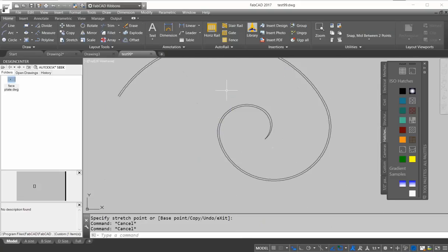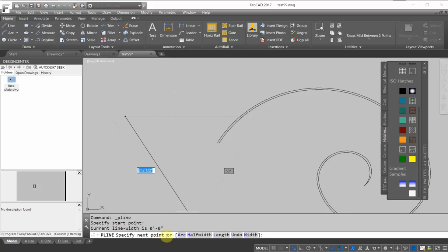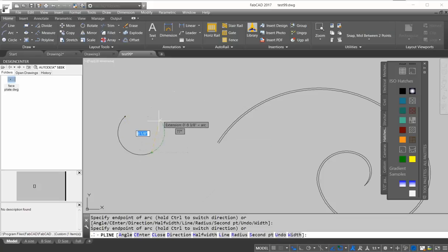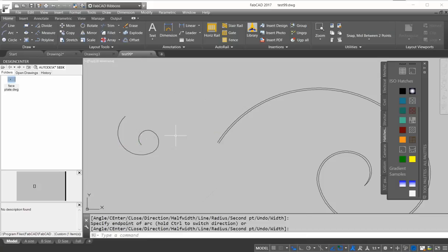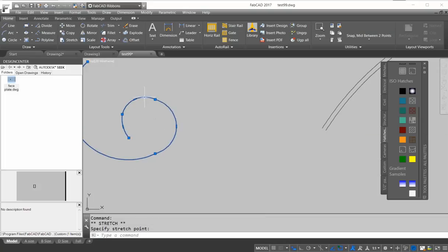All right, now I can use the Polyline command also. So Polyline, and I pick a start point, and then I have arc. But here you see it gives you a view of it at the very beginning. So then I can just click and then just draw it around and do that. Okay, and then I can click on this to modify it. These have gotten a lot easier to modify because they have these extra grips in here now, these little rectangular ones that help shape things.